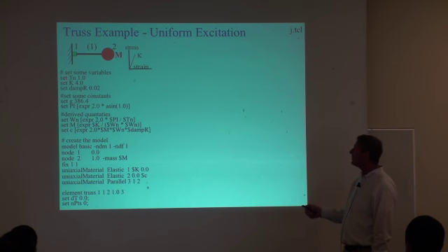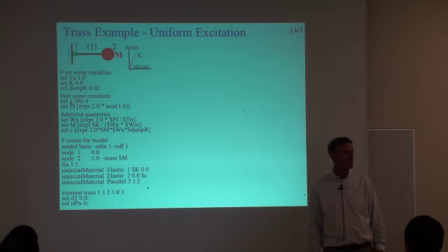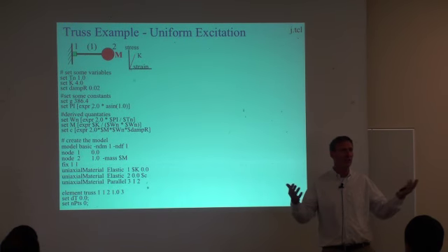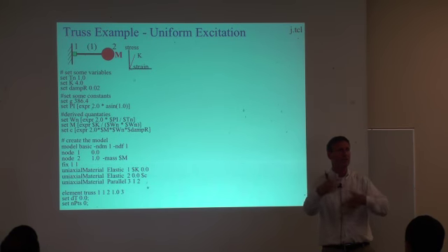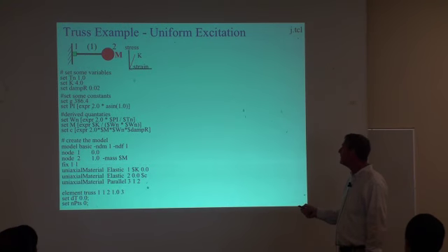In my model, I'm just going to set some period, and I'm going to let OpenSees do some calculations to figure out what mass I need to use given the period I want in my model. Okay? So in this case, I don't have a model in mind where I know what the period of the structure is. Let's go, give me my model based on the period I want.